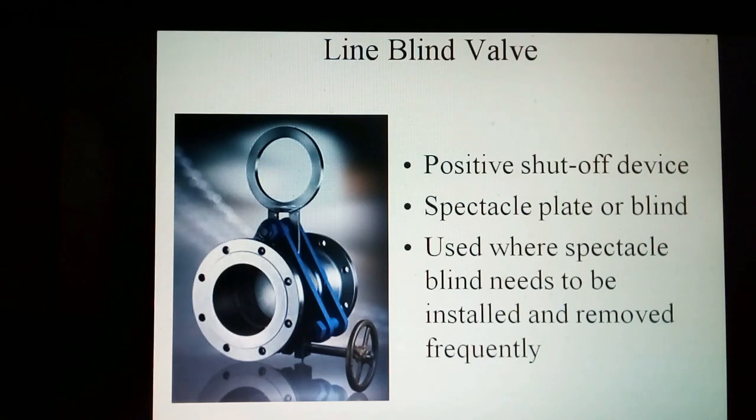As soon as the pipeline is drained, the cam mechanism can be opened by turning the screw or hand wheel. The spectacle plate can be turned and positioned, and finally the cam mechanism can be closed again by closing the hand wheel. Their primary use is to completely close off the downstream portion of a pipeline in a safe way. They are frequently found in the petrochemical, steel, pulp and paper, maritime and oil and refinery industries. They are often referred to as spectacle blinds, spectacle plate or paddle blinds.